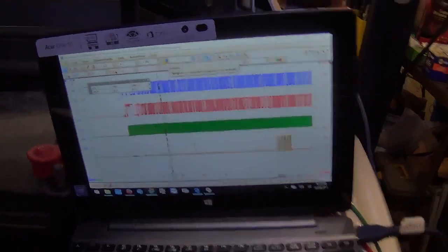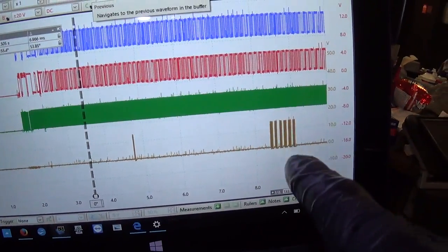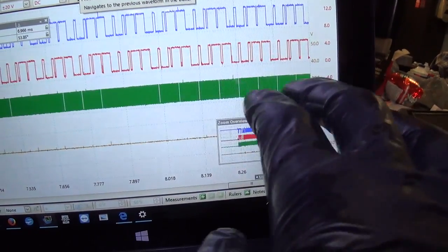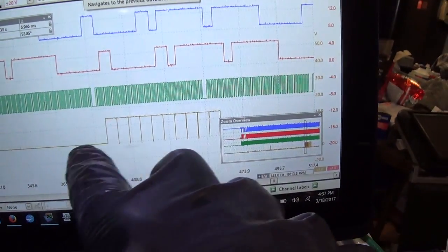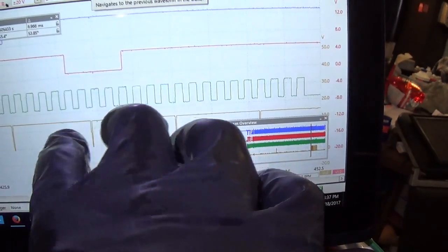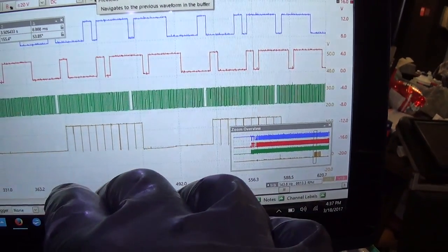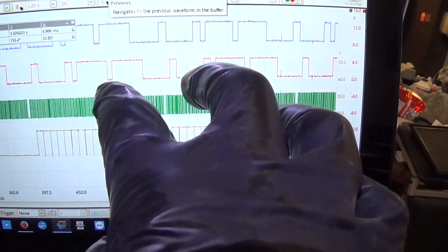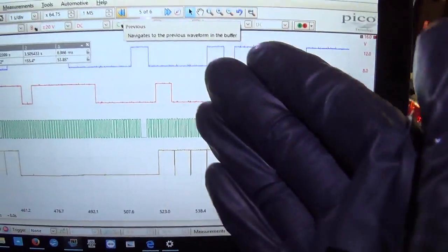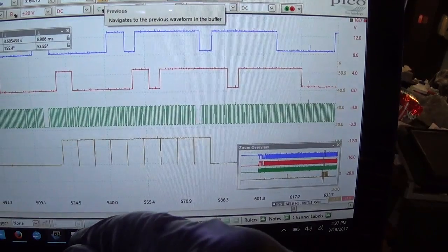And again, let's save this waveform and take a look at it. So this is really pretty neat. You can see on the intake side, that control wire, it tried to do something right here. What did it try to do? That is a weird waveform. It tried to energize that solenoid for sure. Now look at our correlation again. Our intake is advanced with respect to the exhaust. We can put in more cursors, but that probably didn't change.